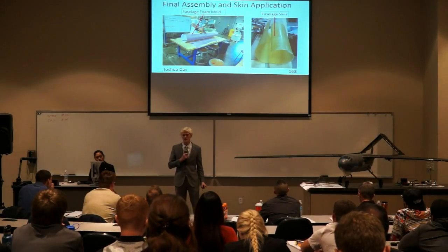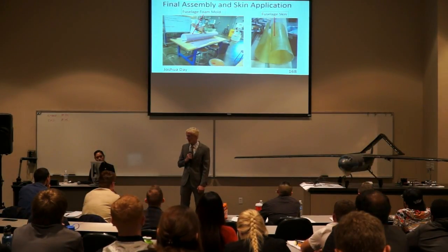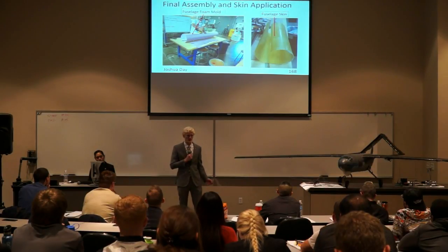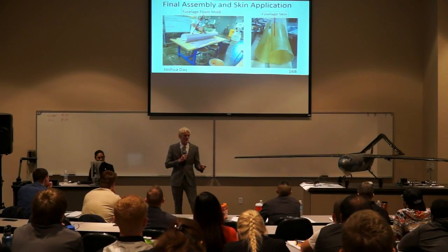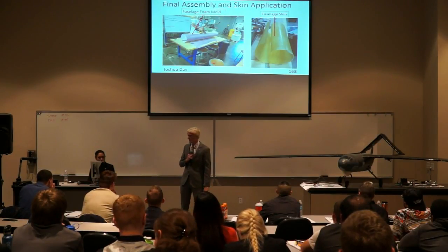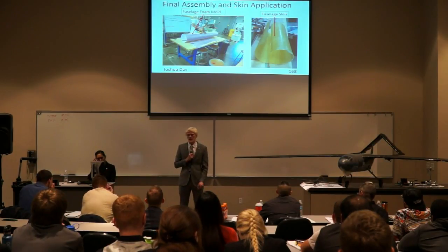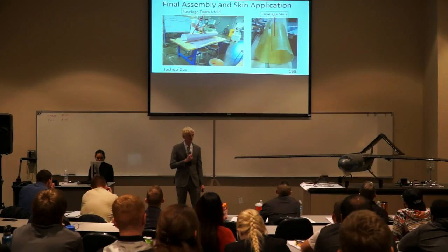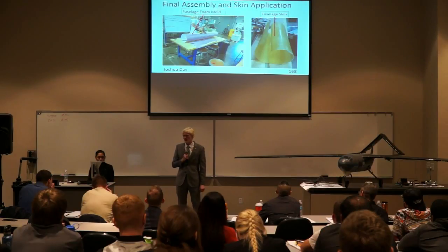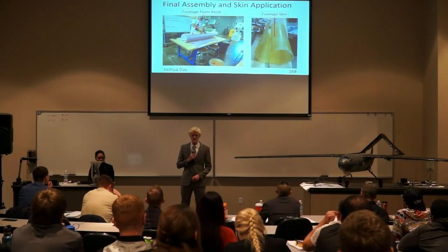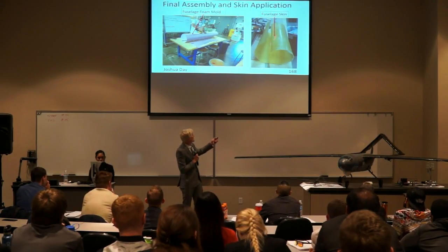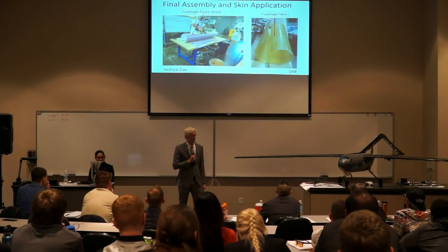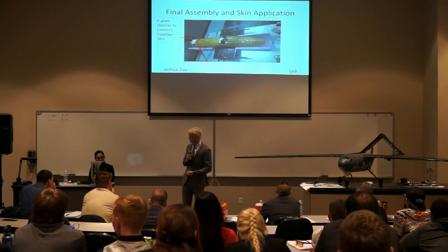To make our fuselage skin, we created a foam mold and cut that using the hot wire, and then sanded it down to make it as close to a perfect circle as we could. We also used the aluminum templates to help us cut that. And then we put a layer of quick release film over the mold and a 2-ply e-glass plus/minus 45 degrees skin over that, and vacuum bagged that layup. And then to remove it, we made one single cut because it was flexible enough to then wrap it around our bulkheads and reattach it that way.